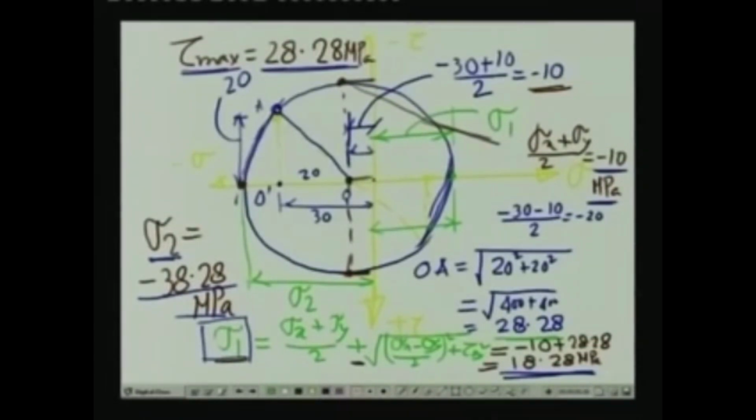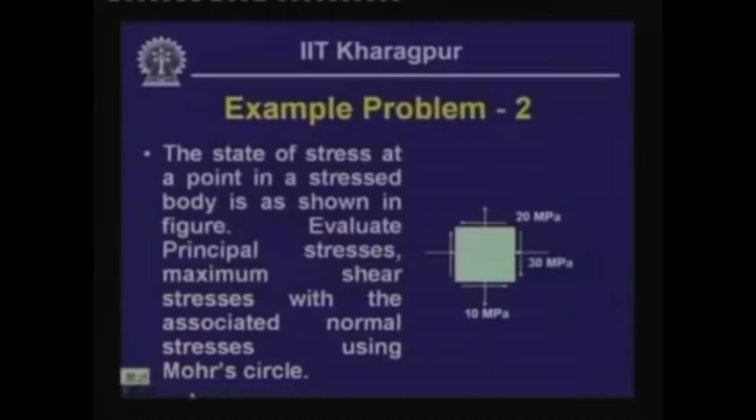With reference to this particular plane, if we go in the anti-clockwise direction, this particular angle will give us a value, half of which is the orientation in the physical plane which locates the maximum principal stress, and perpendicular to that is the plane where the minimum normal stress acts. So, these are the values, and that is how we can compute the stresses using the Mohr circle.